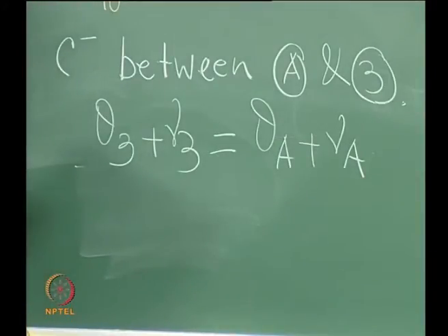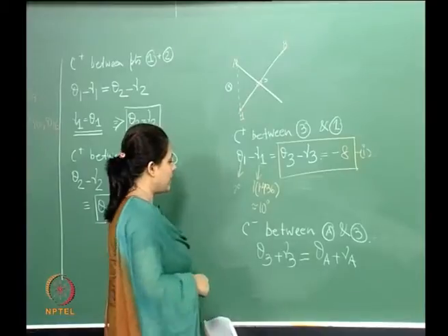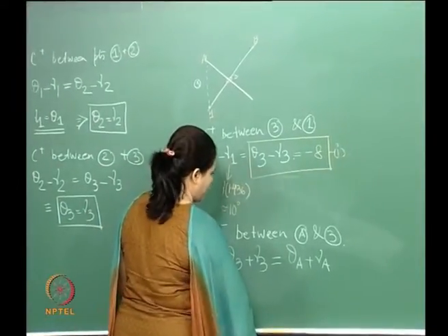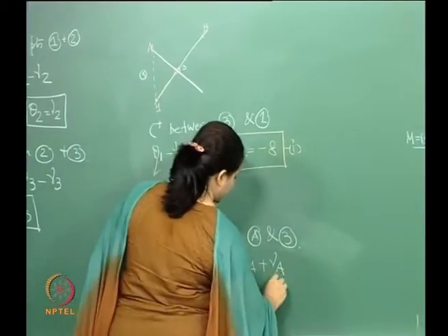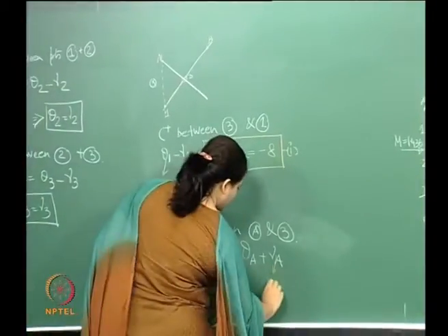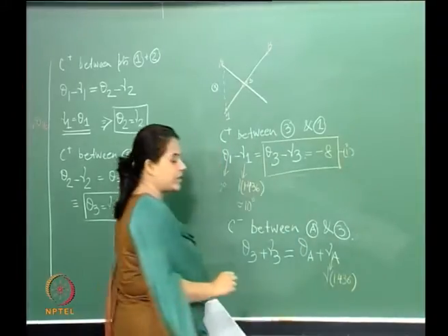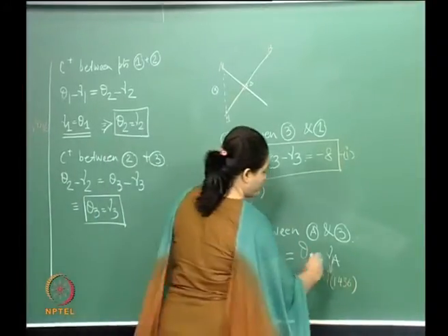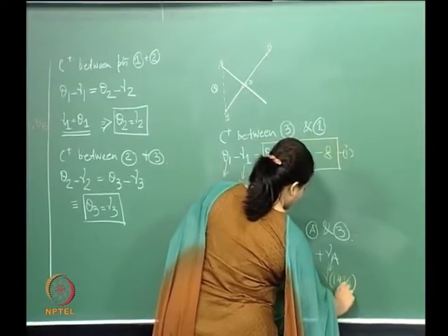Right. So now if I have this, what is theta A and what is mu A? Now mu A is again this. So mu A out here is again mu 1.436, isn't it? Because this is also at the inlet, this is also equal to the Prandtl-Meyer function corresponding to 1.436, and this is again around 10 degrees.